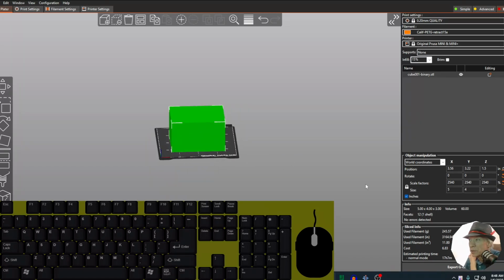But if I flip this, printing on the Z is the slowest. The X and Y are pretty fast with the printer, but every time you go up to Z, it has to retract the filament and then extrude it and go back and forth, and it takes a long time when it does it thousands of times like that.